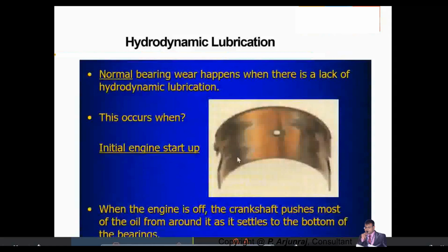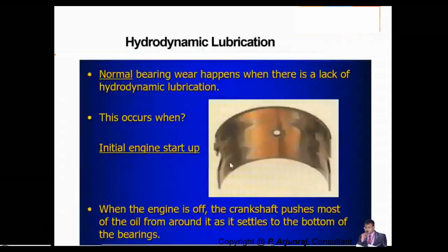See, this is the bearing. If there is no lubrication, or when there is no hydrodynamic lubrication, you see there is a change of color happening. Normally it will be a different pure color. You have seen the bearing how it looks initially, and you see there is a discoloration happening.